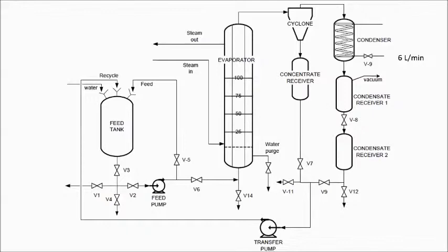Before the experiment is started, ensure that V7, V9, V11, V12 and V14 are closed. Open valve V2, V3 and V5, while close valve V1, V4 and V6.